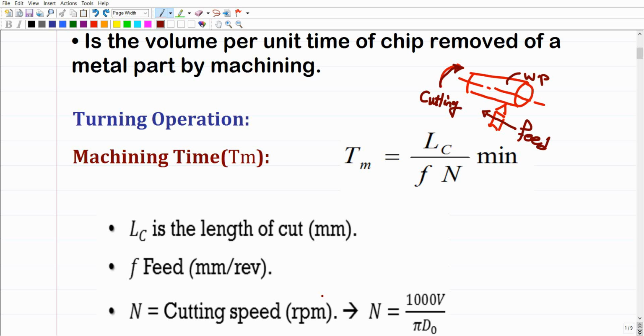It means that at the instant that you stop the cutting motion, you're going to find the tool will be stopped as well at the same instant of time. It means that they are related, or in other words, we're going to say that the cutting speed is definitely related to the feed speed. So this relation, we have to understand it, and they are related through these equations.